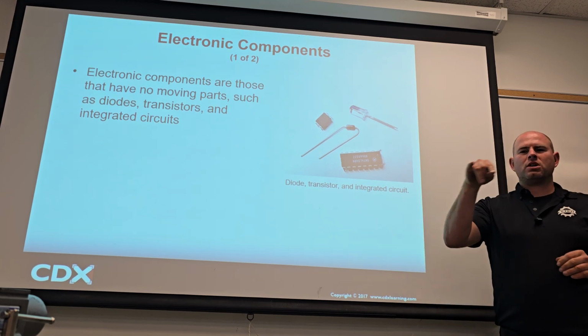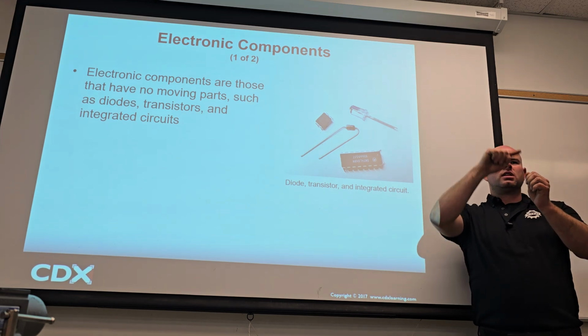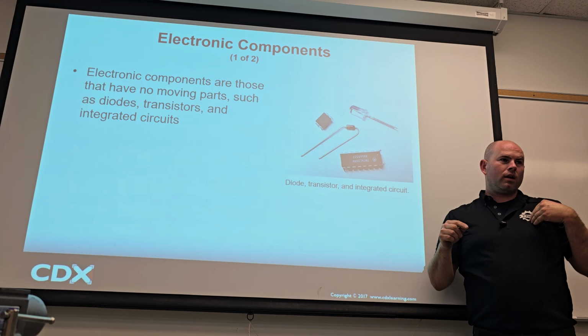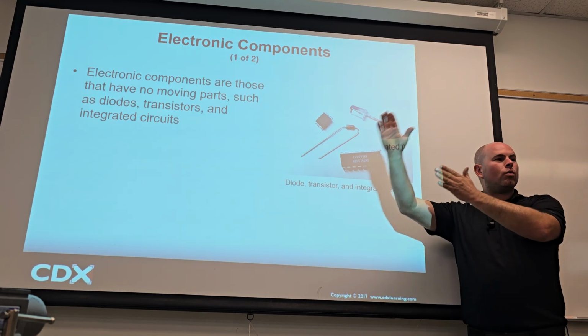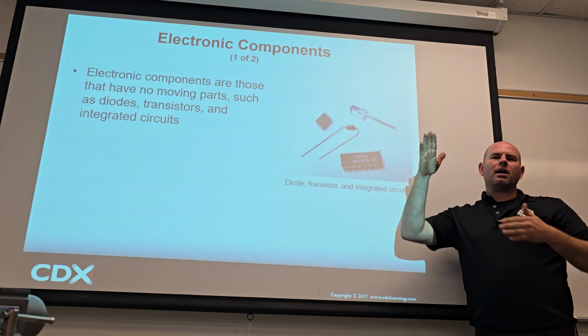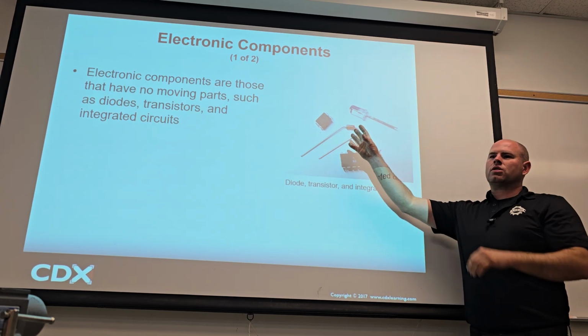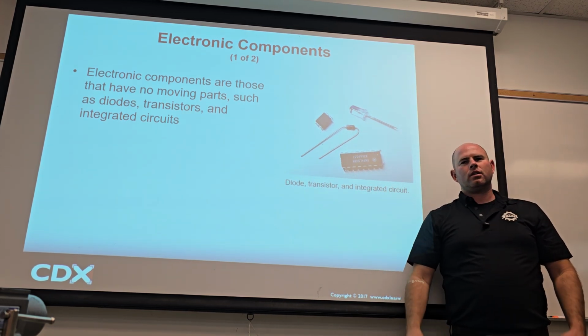Sometimes what we'll do is not just measure voltage. We'll put the oscilloscope on it. That'll show us the waveform, and the waveform can tell us a little bit more, because that sensor has to read off a spinning wheel on the crankshaft. And what if you had a bent tooth on the wheel? You could go crazy with the electronics just to find out there's a bent tooth on the wheel inside the engine. These types of things.